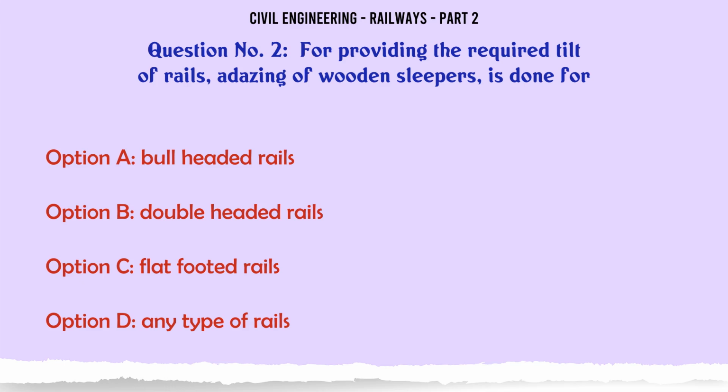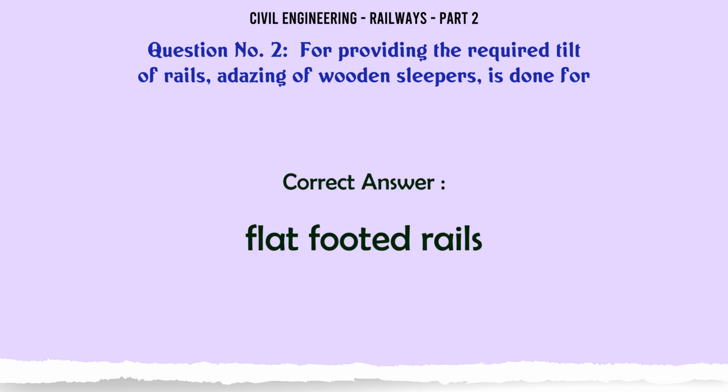For providing the required tilt of rails, adzing of wooden sleepers is done for A. Bull-headed rails, B. double-headed rails, C. flat-footed rails, D. any type of rails. The correct answer is flat-footed rails.